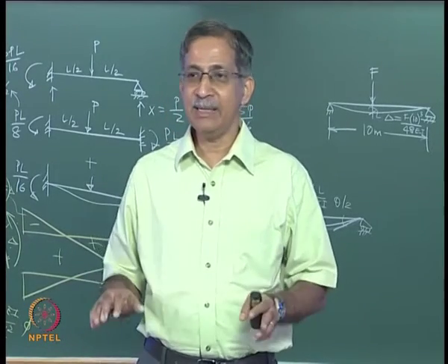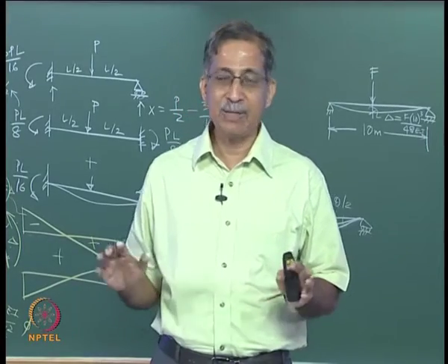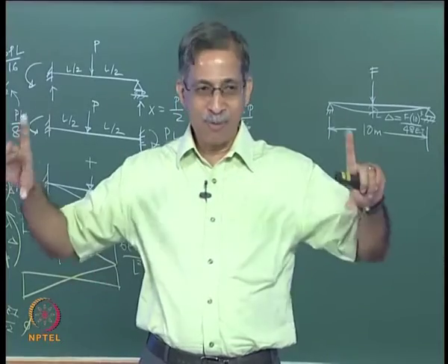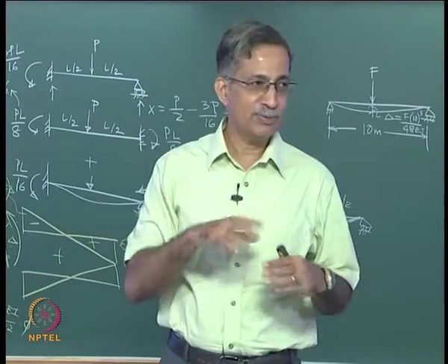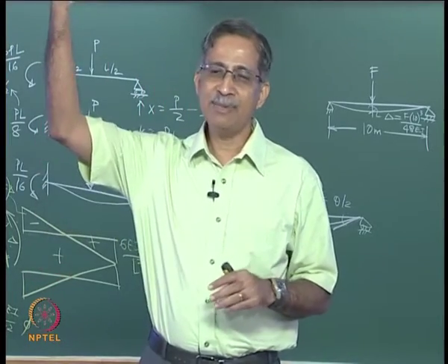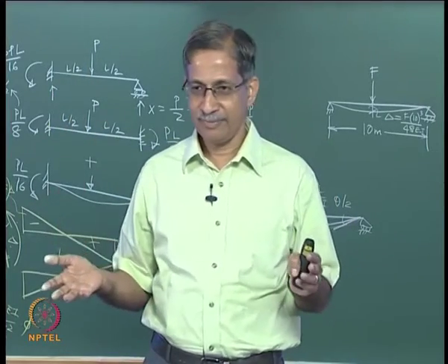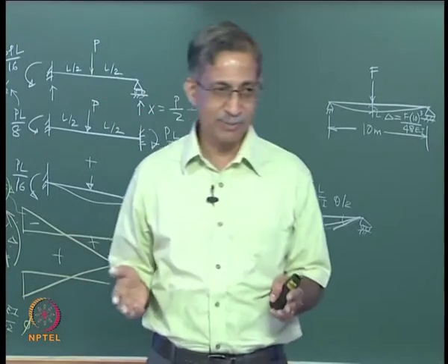For gravity loads they use a concept which we will see a little later called substitute frame method, where they just took one floor and they assumed that the columns were fixed at top and bottom, so it was much easier to analyze. The argument was whatever happens far away from this story is not really going to affect that floor. It is a hunch which works out well, you can prove it with Muller-Breslau's principle.